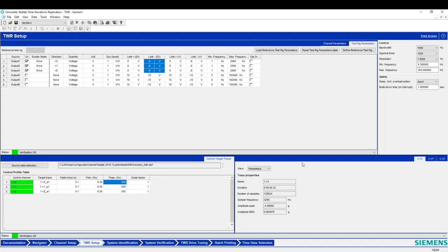Here on the right we can have a look at some parameters. For instance, in the X direction we have a duration of 40 seconds with more or less an RMS value of 1 g, of course. The same for the Y direction and the Z direction.